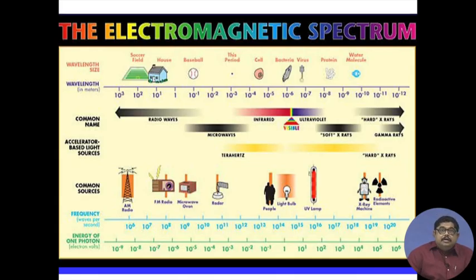So all these are part of the electromagnetic spectrum, but as you can see from this slide, there is a broad division of radio waves and microwaves. Roughly, from kilohertz sort of frequencies to gigahertz sort of frequencies we call radio waves, and a part of that, 100 megahertz to 100 gigahertz, is called microwaves. So basically in this frequency range we have certain techniques to handle all these applications.